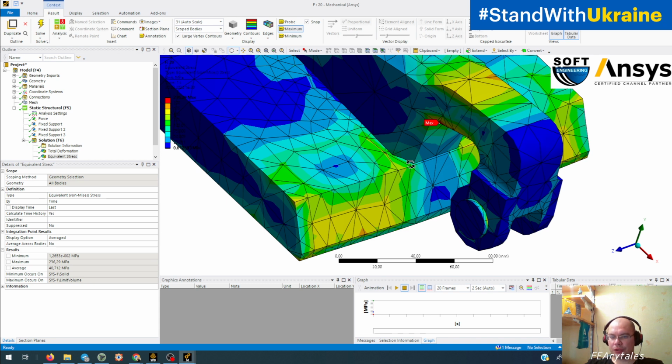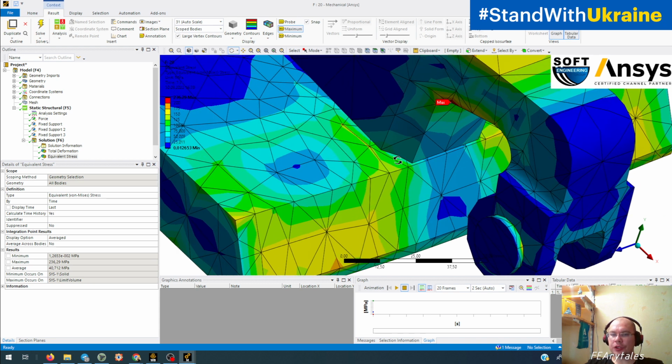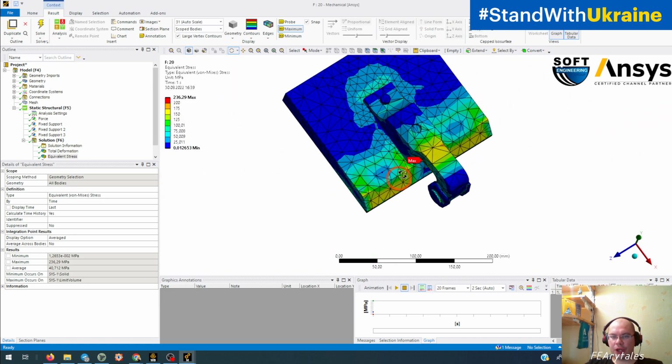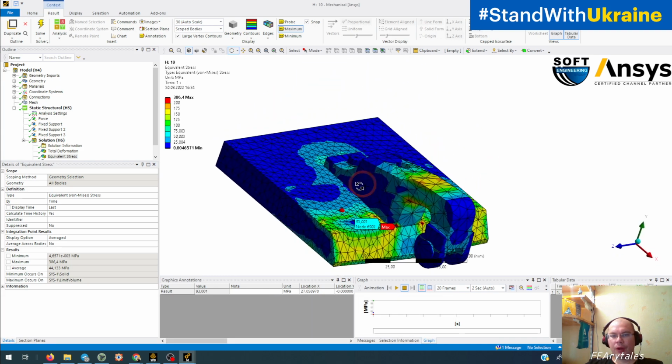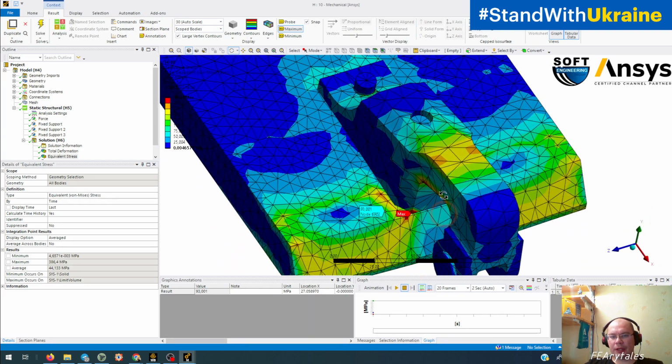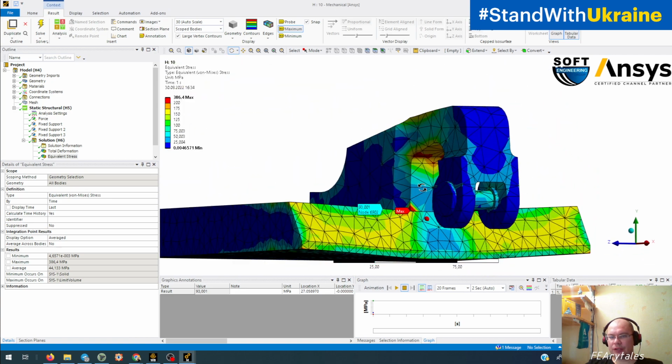In coarse mesh, we average all stresses over very big elements. So sometimes we cannot obtain the place of hotspots, not obtain the real places with problems. So you need to change your mesh to obtain good stress distribution.